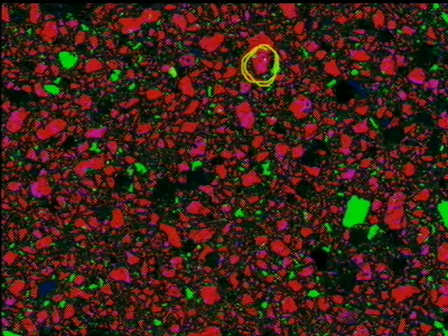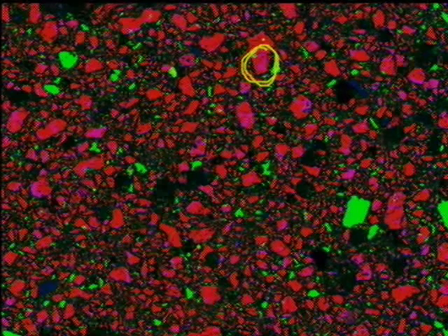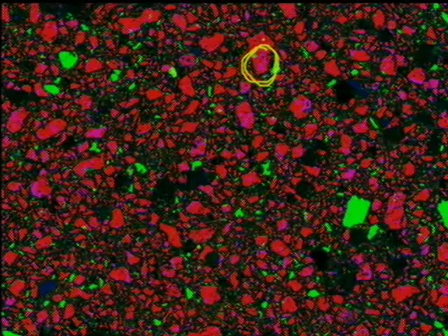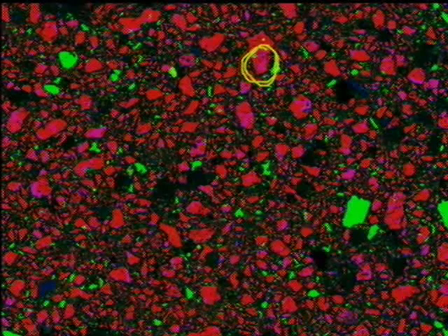What you will notice is that there are regions that are a dark red, and there are regions that are the lighter pinkish color. The lighter pinkish color will be your C2S. The darker red will be your C3S. And one of the things that's important to notice here is you have a lot of these particles that are made up of more than one of these particular compounds. So they will be coexisting. And this is an important understanding because it's not like we've got C2S particles and C3S particles, but we have all of these inside of the overall system. So we'll change our color back.